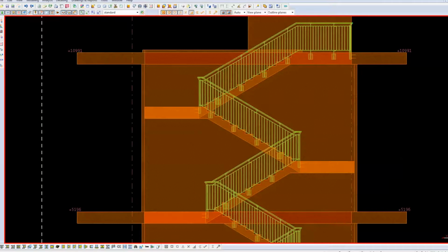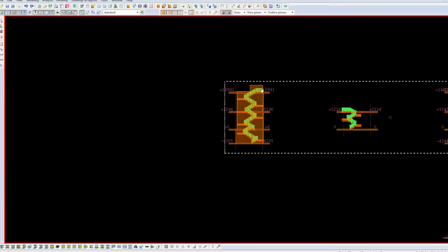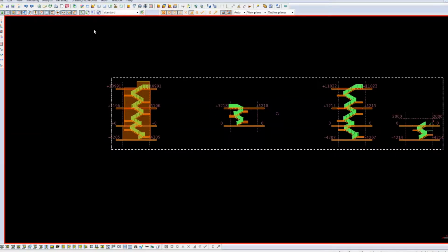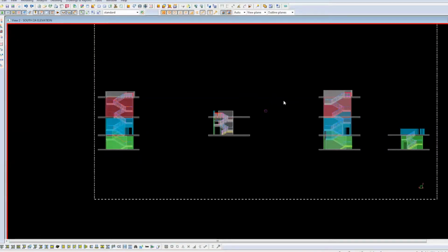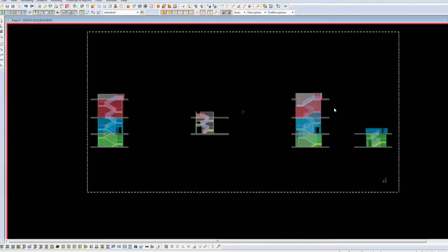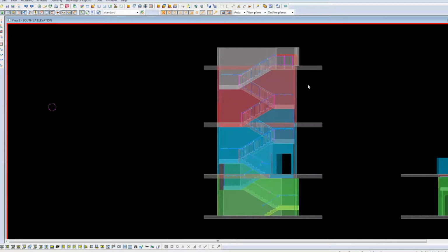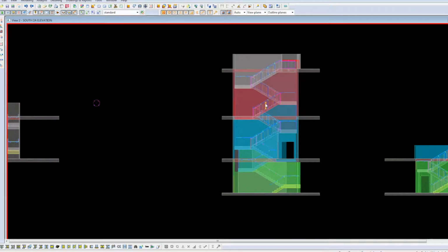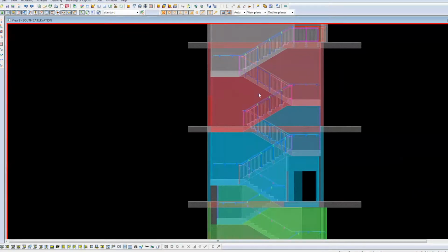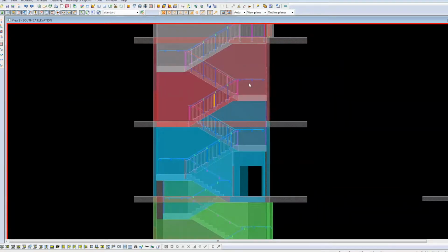Now the model that I'm about to open is actually same site, same job, just a different set of stairs. In fact, I'll show you. So this is the fresh model. This is the model that I issued from, and once I'd done all my angle justification, void width justification and flight width justification, I set about remodeling it and completely changed the way that it would detail.